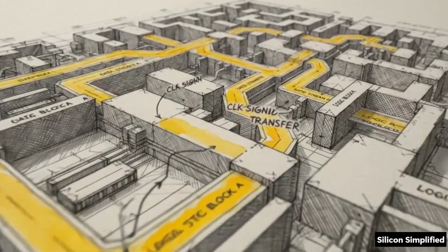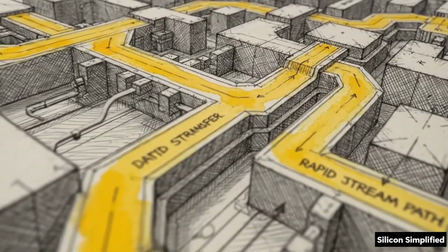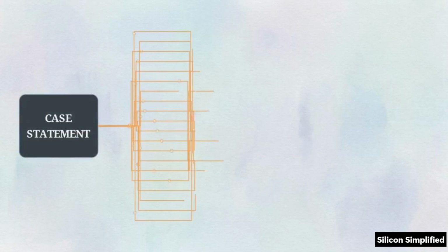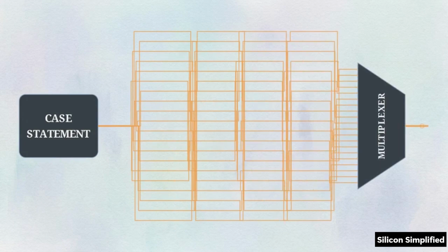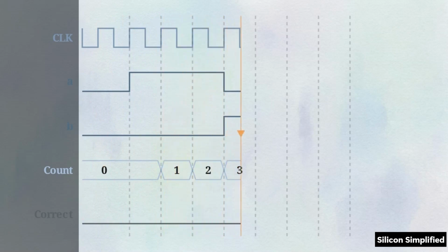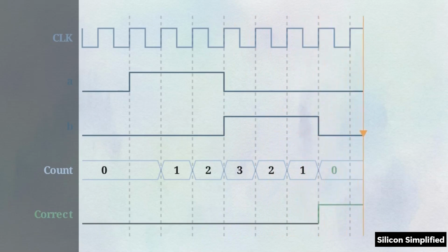It analyzes our cleanly separated combinational and sequential Verilog blocks and begins routing physical paths. The software maps the sequential blocks into physical D flip-flops to hold state memory. Simultaneously, it weaves the combinational case statements into complex multiplexers for logic routing. This timing waveform chart shows the final validation of that hardware. When we feed an input stream of 3 A's followed by 3 B's, we see the counter value step up, then decrement perfectly back to 0, snapping the final validation signal high.